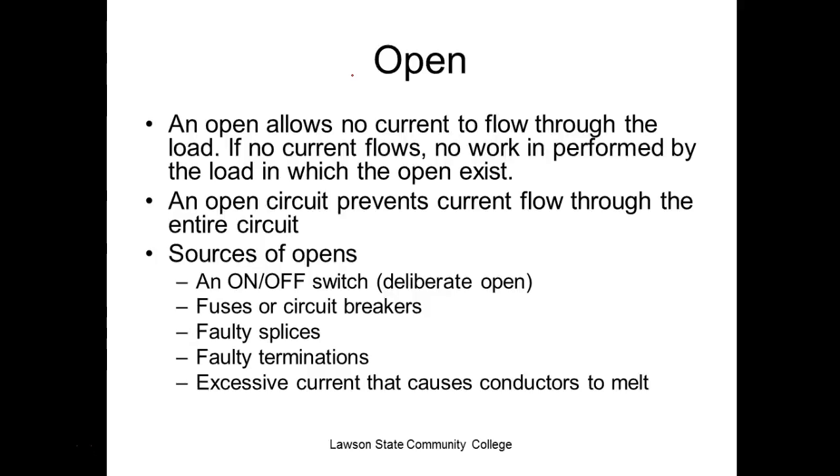I've seen electricians get into a place where none of the breakers are labeled, and they can't turn off everything to figure out which one does it. So they'll deliberately create a short circuit. I've seen them deliberately put wires in a plug and trip the breaker, so they can figure out where it goes. In that way, they don't have to kill everything.